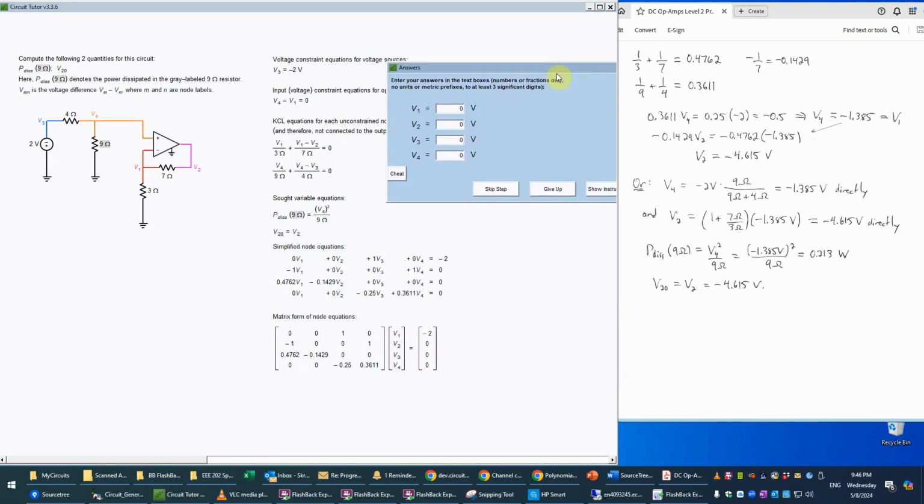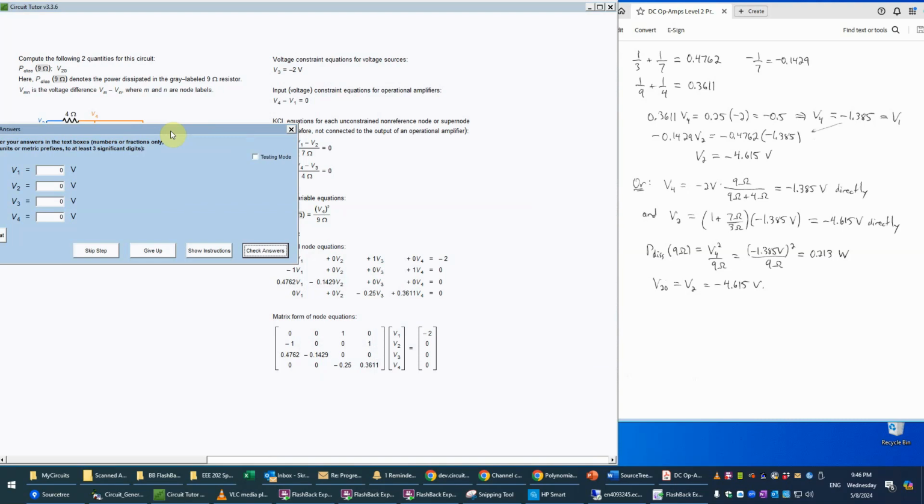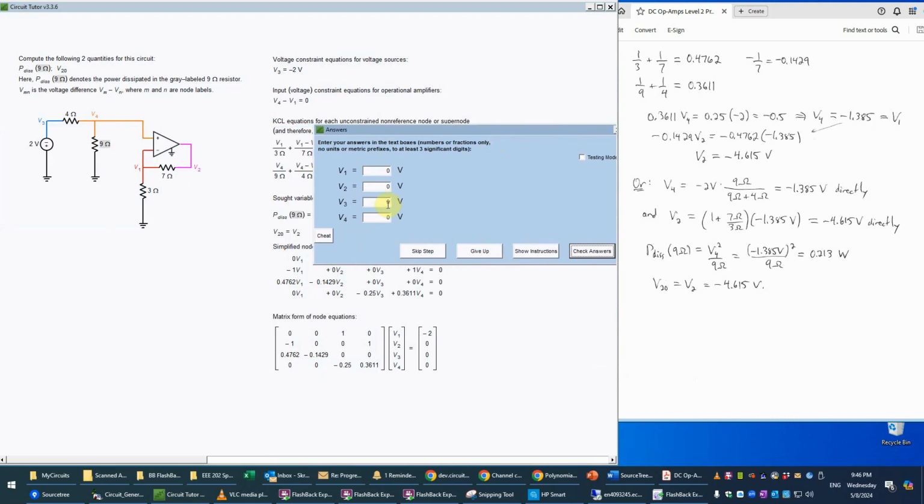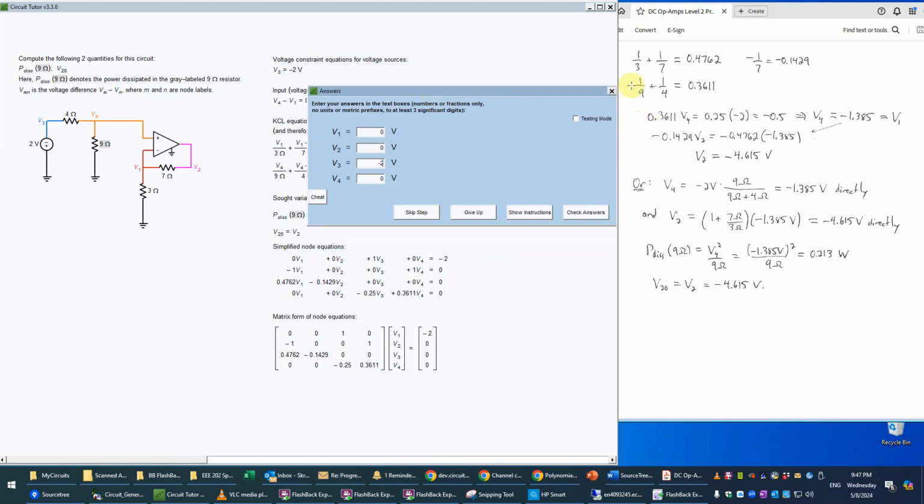And here, if we look at it, V3 is just -2. We know that one already, so we'll just put that in directly from this equation. V1 and V4 will be the same, but we need to solve for those. So let's start out by solving for V4. In order to do that, we can use this bottom equation that involves only it and V3, which we already know from this equation.